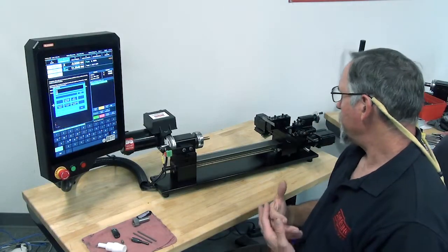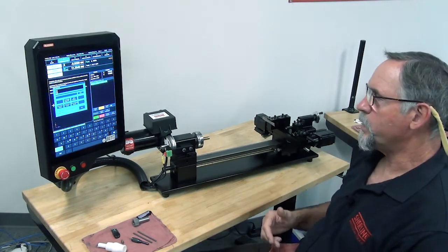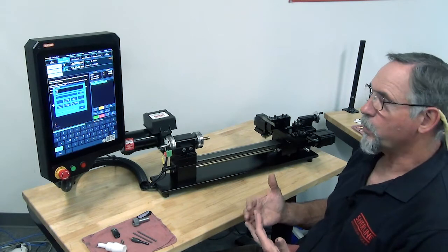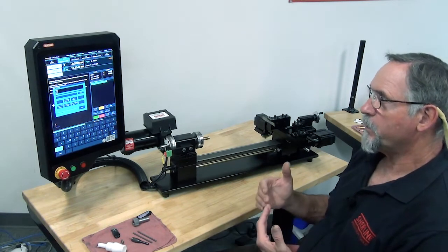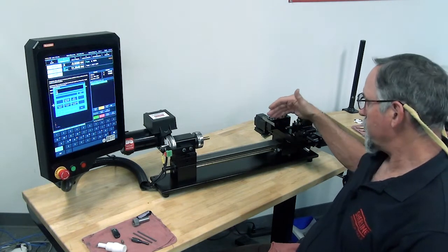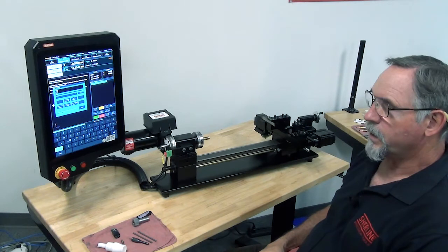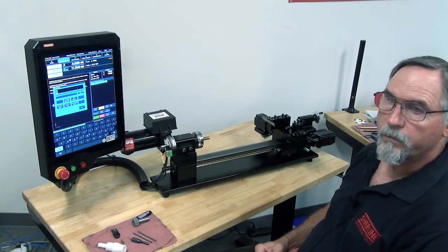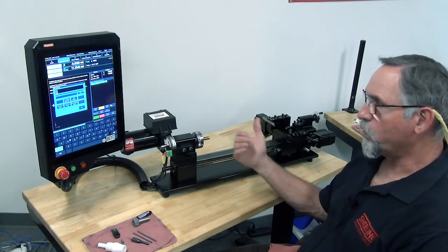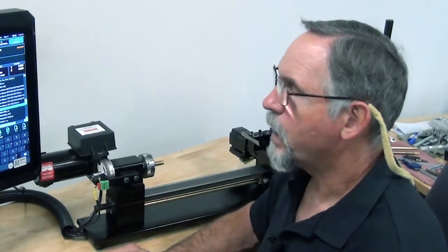So those are some tips on things you need to think about as far as your tool relationship to each other when you actually run your program. As soon as you call up a different tool, all it's looking at is the information for that tool. It doesn't know where this other tool might be, so you have to do some editing on a lot of your programs just when you go from one tool to the next so that you don't crash. And we'll go over conversation next.